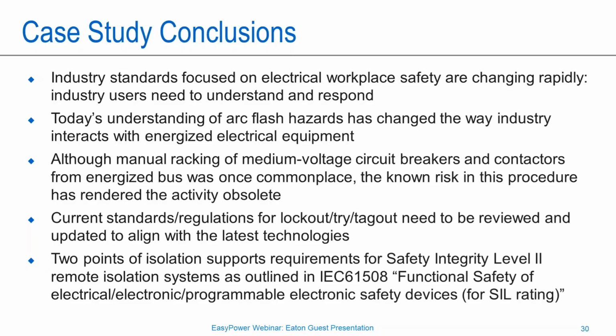And this last point probably would require another webinar, but I've been involved in some of the standards around 61508, which is a functional safety standard for safety integrity level, SIL, systems. I think this integral racking functionality that I showed you is maybe a piece of that puzzle. It's an opportunity to move towards functional safety and possibly remote isolation, where isolation of electrical systems can be accomplished remotely. There's going to be lots of headroom moving forward, and lots of opportunity for new applications around electrical safety, driven by not only the standard, but also new products available from manufacturers that support a safe workplace environment.